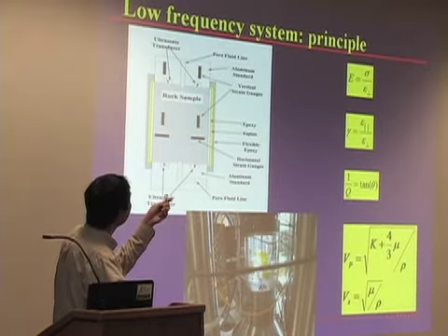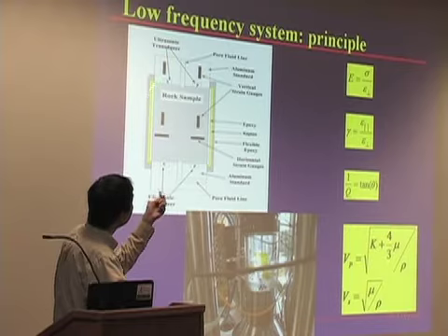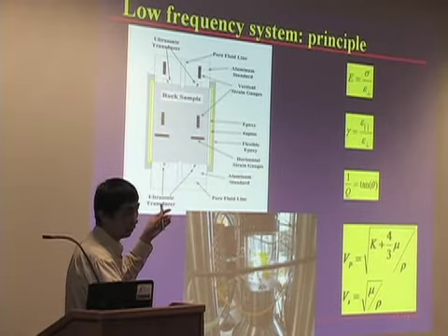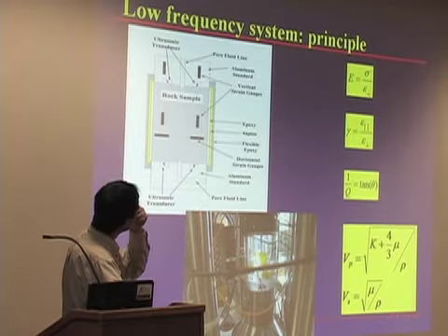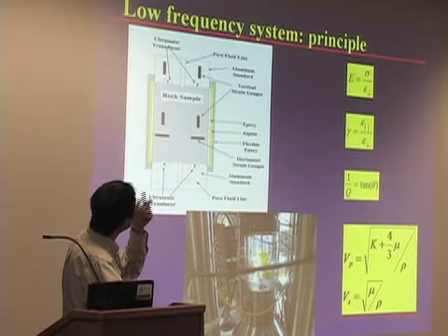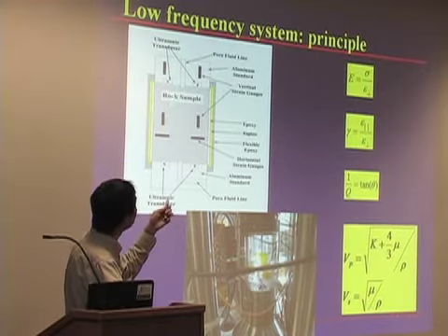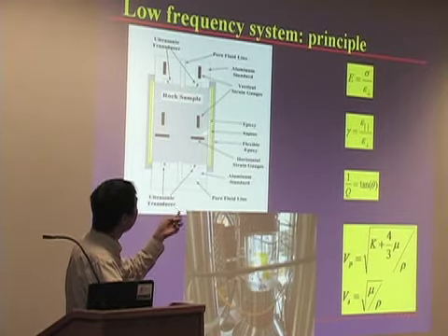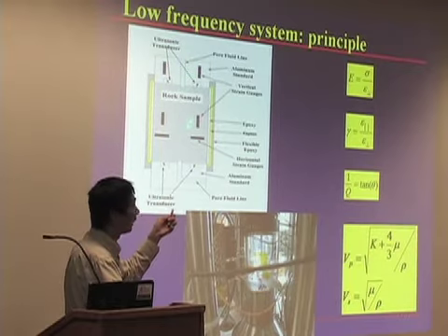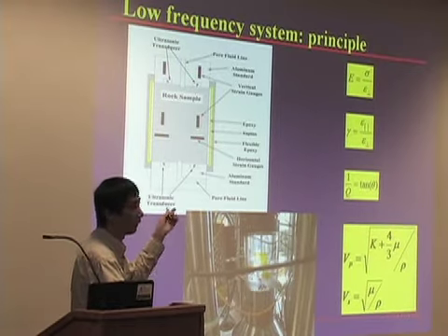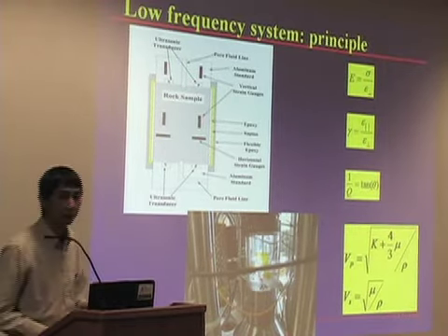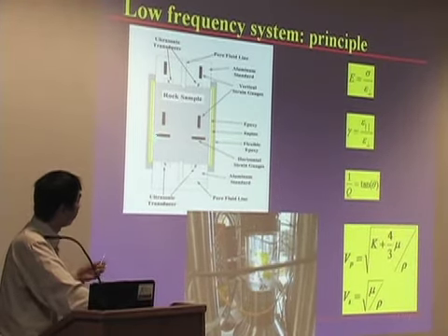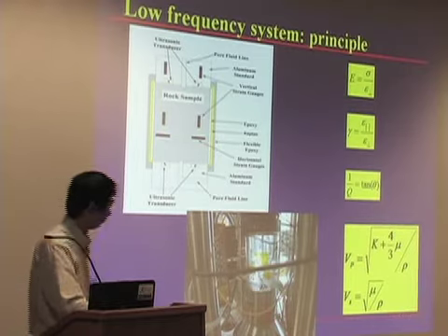With this kind of configuration, it is under the iso-stress condition. That means the stress everywhere is the same. We just need to compare the strain output from the standard material and our sample. Then we can relatively calculate the Young's modulus and Poisson ratio of our sample.